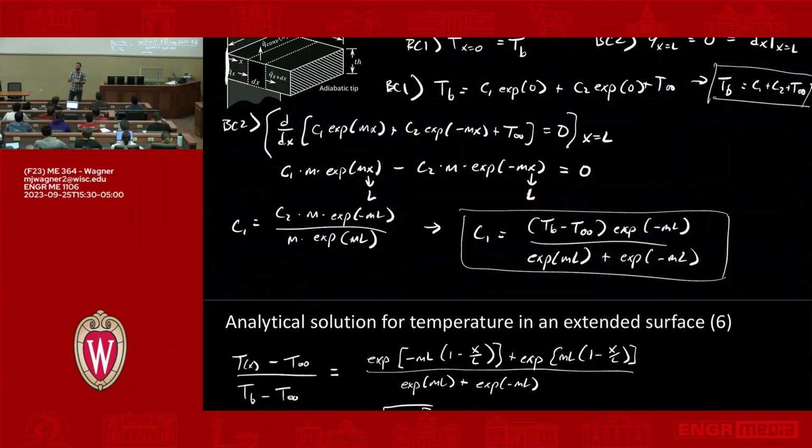So what I told you in the problem is to just assume a T bar. Remember we talked about this radiation approximate formulation? Assume a T bar and just leave it, don't update it at all. That will make the analysis possible. Otherwise, you're going to end up with T to the fourth, which is a nonlinear, non-homogeneous ODE, and you won't be able to solve it.